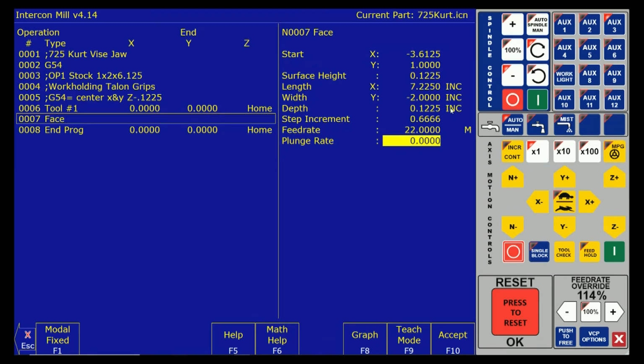In Pro Shop, when you pull up tool RTA3, it's going to tell you which insert is on that tool. And when you go to that insert page, I have data there linked that tells you what the manufacturer says you can use for an SFM multiplier and chip load.